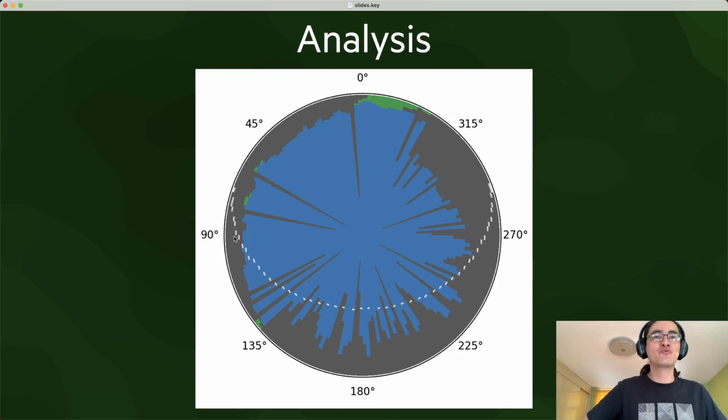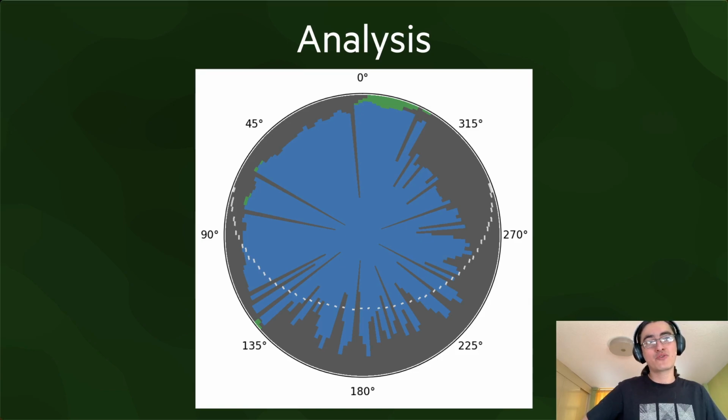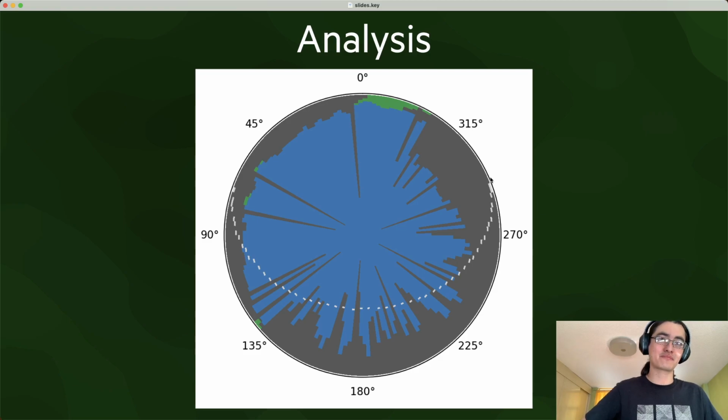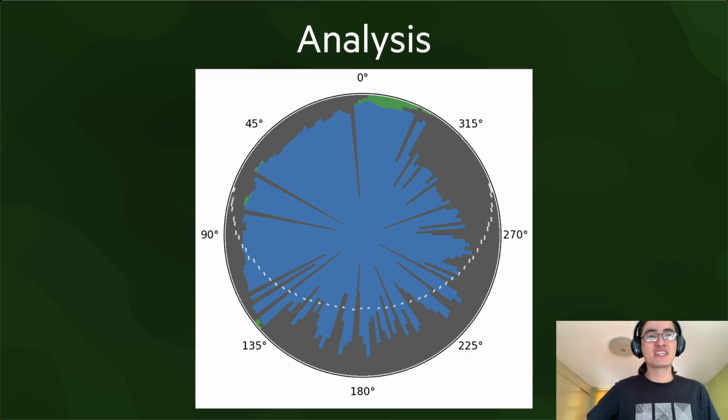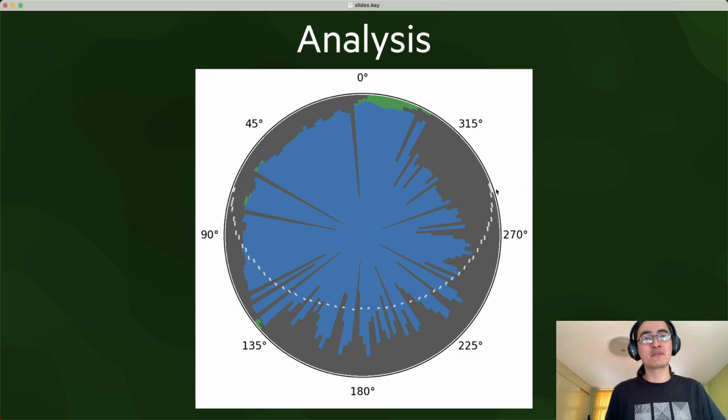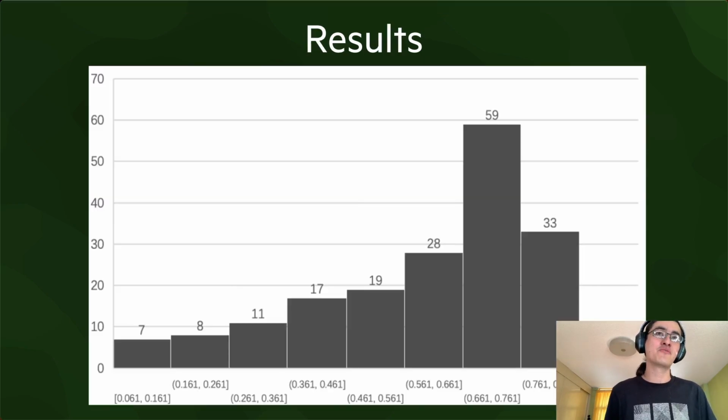So for each of these potential locations, you generate the sky view, and then you look at the path that the sun would take, looking at the solar parameters for a given day. And then you can see for a given location when it would be hit by the sun and when it would not be hit by the sun. You can match this behavior to the behavior that we see in the temperature change to guess the correct location. And then based on the behavior of the sun, you can also know when to discard the data or not to discard it for urban heat island results.